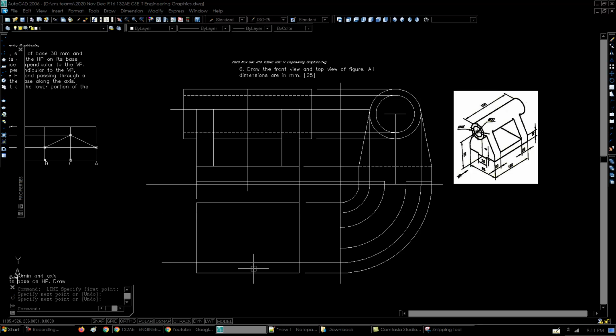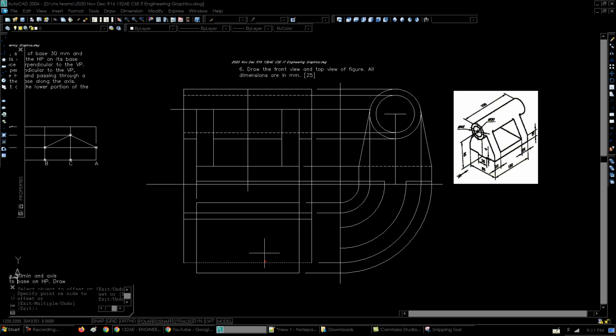So this is the outer cylinder. Fine. This is the outer cylinder, and that outer cylinder is starting at this point. So I'll have to draw a projection line up to this point, and I'll have to break this apart. Okay, so this here is the outer boundary of the outer cylinder. Now the hole, of course, is going to be coming inside of it. So I can just take this distance and take offset of this, apply these invisible edges over here. But of course I'll have to draw these edges, take arcs, and continue to do the same procedure for that.